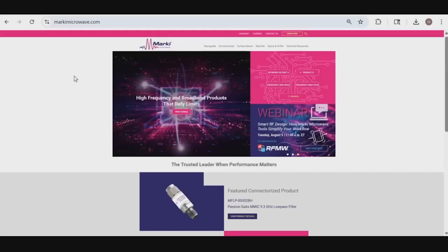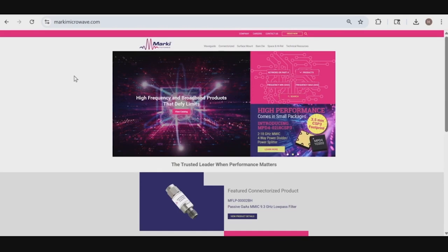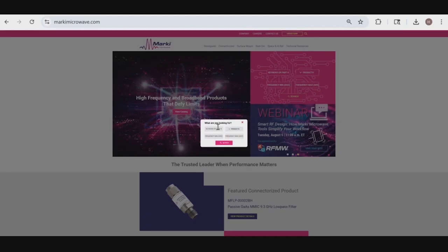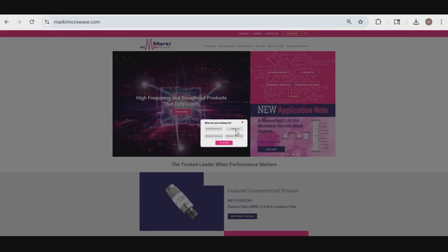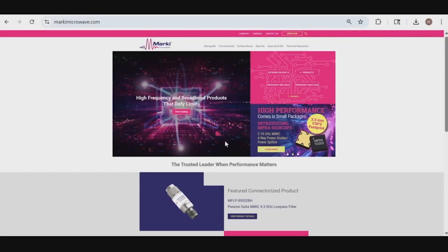And then I'm going to wrap up by showing you how to put it all together for a quick system simulation. Back on the Marki site for the live demo, and now our task is to find candidate amplifiers and use the performance data viewer to compare their performance. So last time we found a mixer, we went right into the package and right into the mixers tab that we wanted. I'm going to show another method of just doing a general search, which is going to be up here in the looking glass. So if we know the part number, we could type it in, but here I just want to see all amplifiers that operate from 20 to 30 gigahertz. I'll go ahead and hit enter.